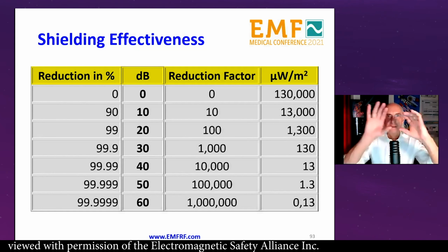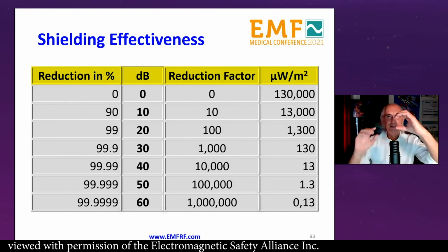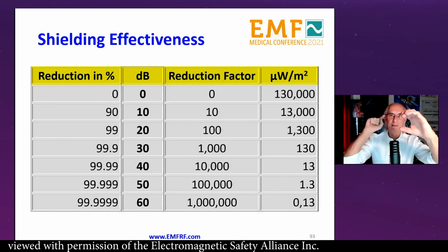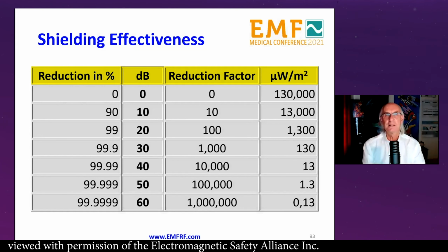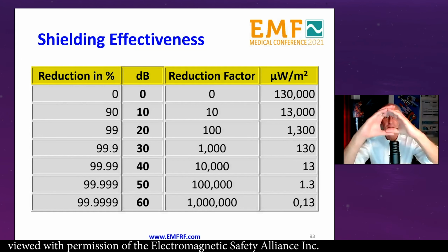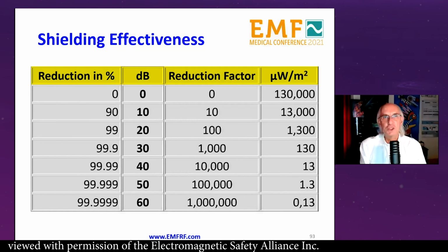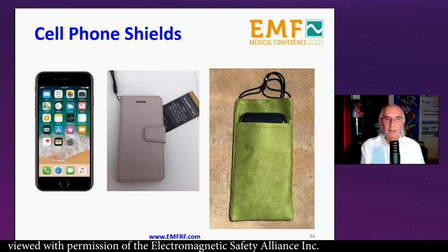Now, there's one flaw in this whole system, and that is when they actually test the materials, they take one piece, and they have an antenna going here, sending out a signal, and an antenna here, absorbing the signal. But you're basically looking at a small surface area. And if you install that material in the building, you're not going to get the same results. Why? Because you got openings, you got windows, you got doors, you got chimneys, you got vent pipes, you get cracks and crevices and so on. So whatever it lists on your material data sheet is not necessarily what you're going to get when you install it. So that's where the measurements before and after come in handy.